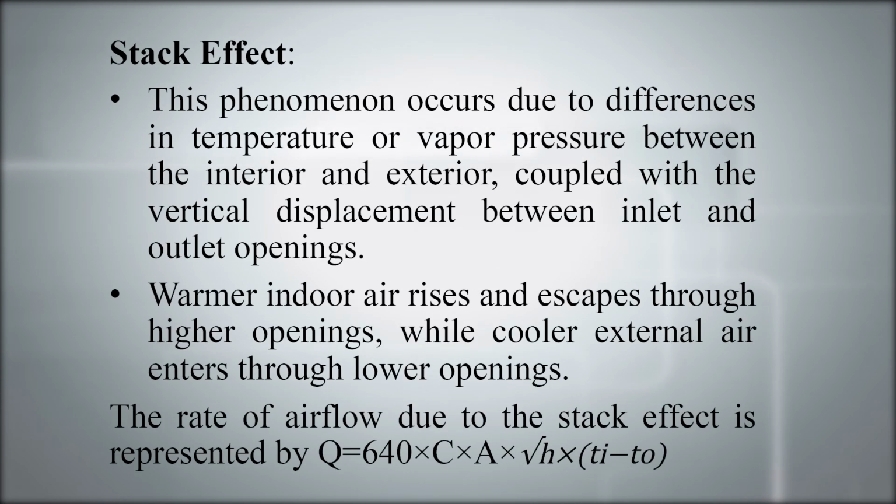Next effect is the stack effect. This phenomenon occurs due to difference in temperature or vapor pressure between the interior and exterior, coupled with the vertical displacement between inlet and outlet openings. Warmer indoor air rises and escapes through higher openings, while cooler external air enters through lower openings.